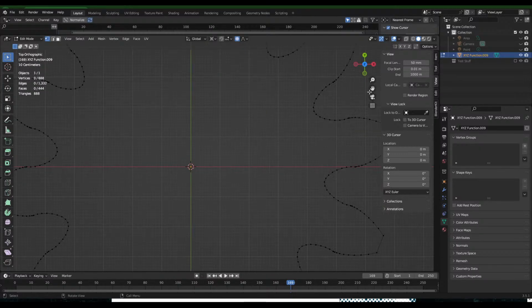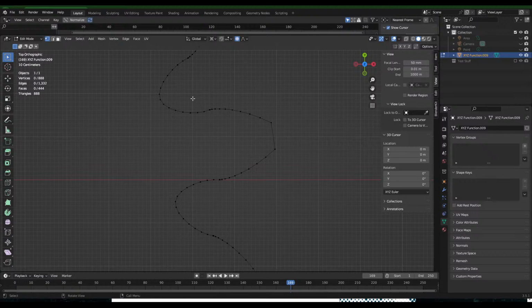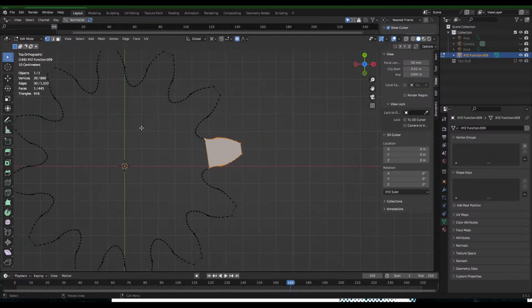So we're going to start by selecting any of the teeth, doesn't really matter, and just select as many points as you want, but make sure they're proportional on both sides. So I'm going to go to these 2 points right here and just select 4 points out. So that should be good. You can do 5, you can do 3, doesn't really matter, but keep it somewhere in that range. If we hit F, that's going to create a face right there, and that is going to be the first step to the top surface.